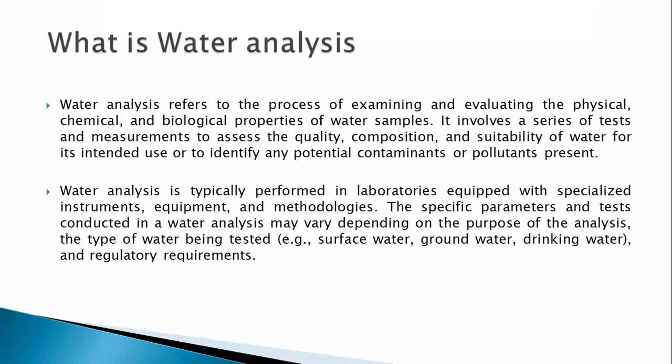You would have sterilized the foil that you are using to cover it before you take it down to wherever you want to get the water source. And even that water source, if you are getting the sample from a tap, you have to sterilize the nozzle of that tap. You can use a matchstick. You just light it up. You are just trying to sterilize the nozzle so that the microorganisms that have adhered to the nozzle, maybe by virtue of somebody carelessly touching it, will all have died. You understand? So you are picking water into your sterile vessel, covering it with another sterile cover, and taking it straight to the lab.